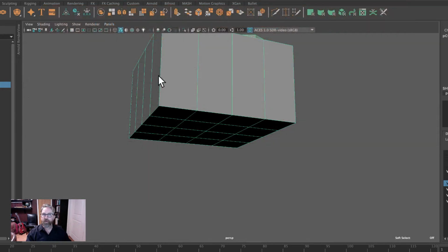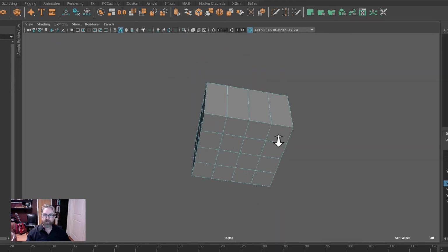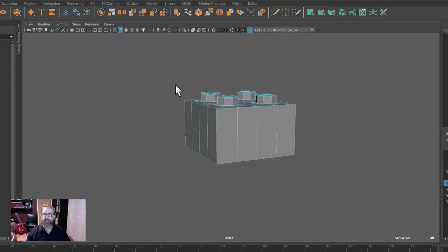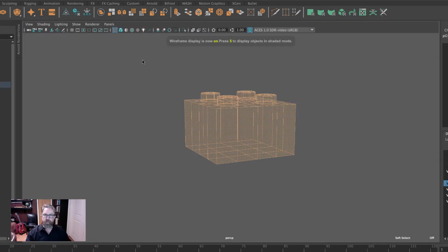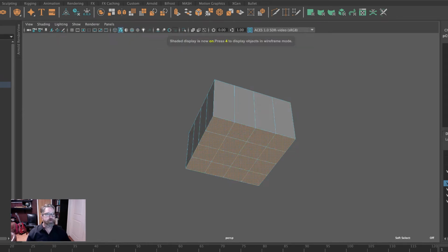So the first thing we want to do is select the faces of the bottom. You could shift select around, but as we learned in the last lesson, we can just draw a bounding box. And then with your control key, draw a bounding box around the faces that you don't want selected. Now we're left with those bottom faces there. We'll extrude, right?